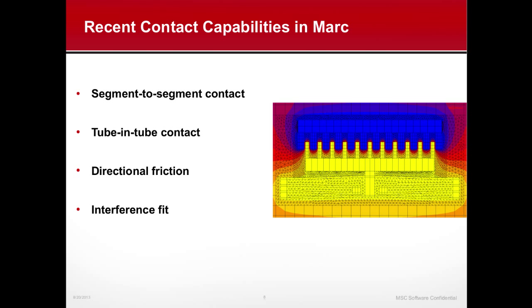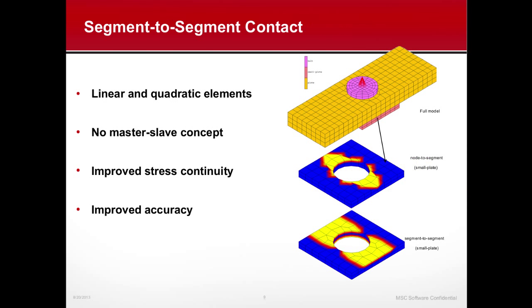And in the next few slides, I'm going to summarize some of the newer capabilities in Marc related to contact. The multiphysics contact capabilities have also been enhanced, but I will not be covering them in this presentation because of the amount of time we have. And so we talked about the segment-to-segment contact approach earlier, and this has been implemented in the past few years.